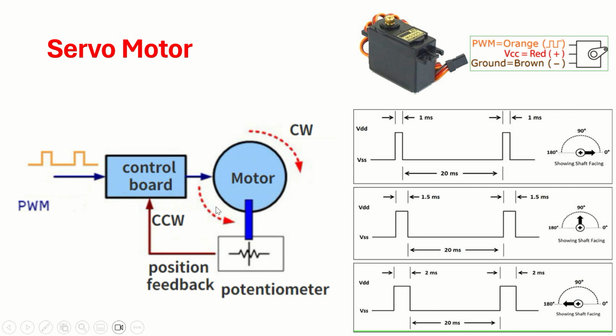So what we are doing is, the closed loop control system is inbuilt inside the servo motor itself, this entire circuit. You don't need a separate sensor externally like in a DC motor. I was telling you we have to measure the displacement, but here the displacement is automatically measured by the motor itself. That's the beauty of the servo motor for accurate positioning, since it has an inbuilt sensor. Second, it is easy to control because what you give is a pulse, and the width of the pulse you are controlling, so the displacement and the direction are indirectly controlled.